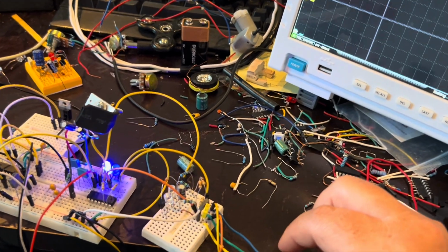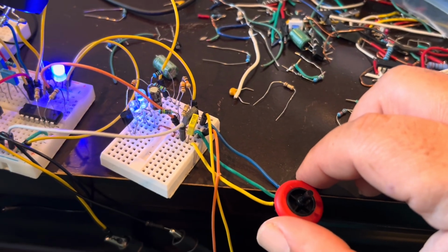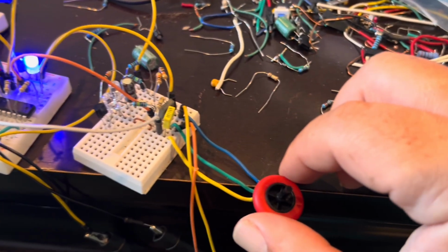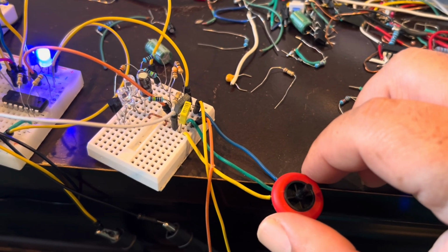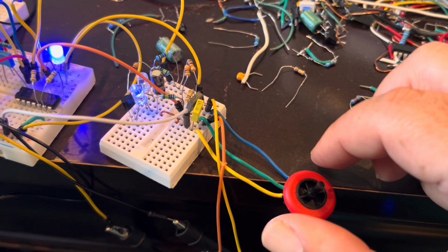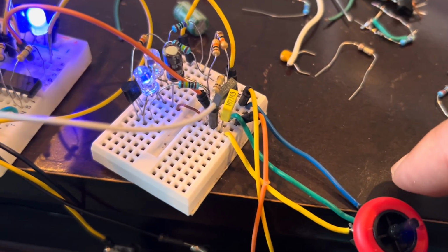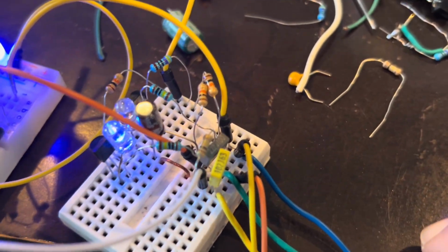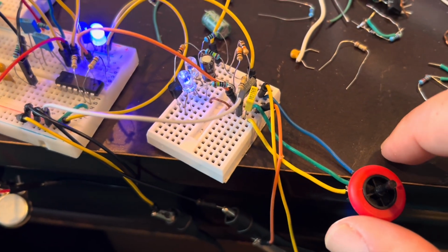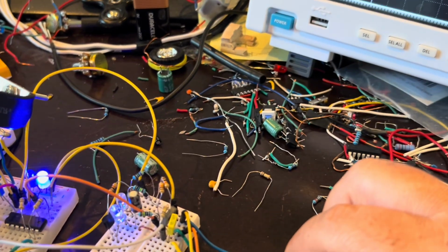Now, using that same logic, if I'm turning this counterclockwise now, so counterclockwise mode, the B pin goes on first. That's the clock, rising edge. So that rising edge of that clock went on while the logic level of the data pin, which is the A, the light on the right, is low.